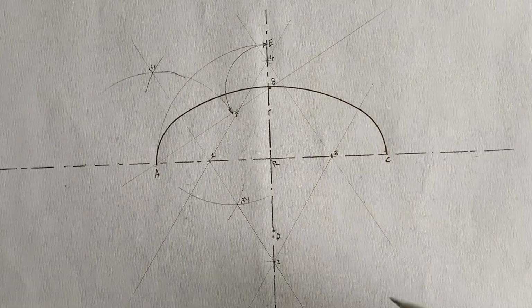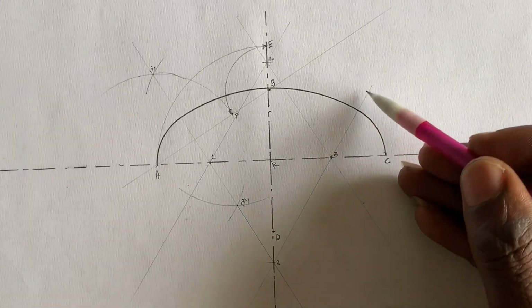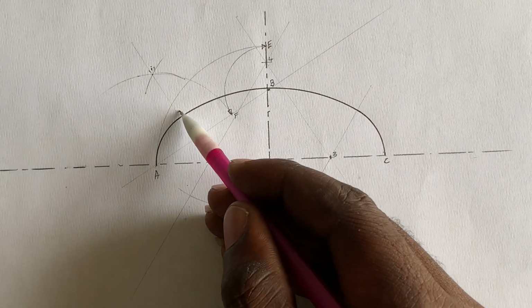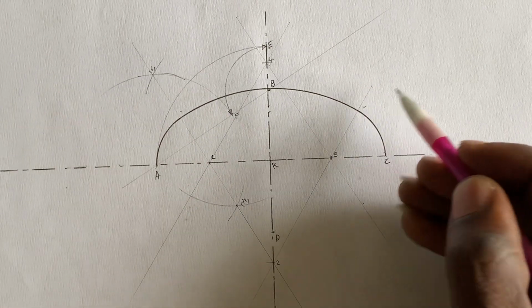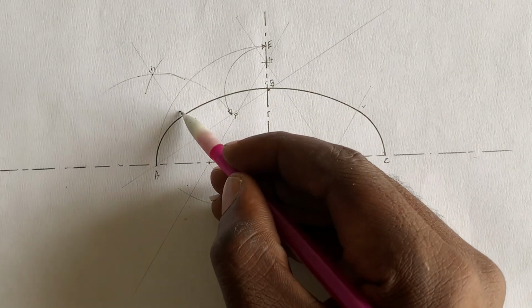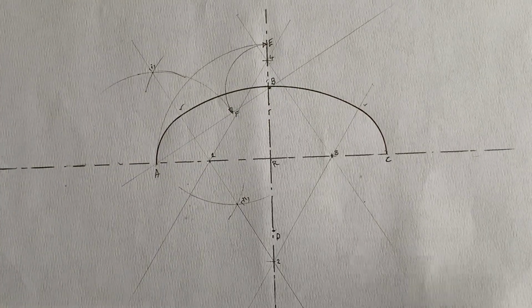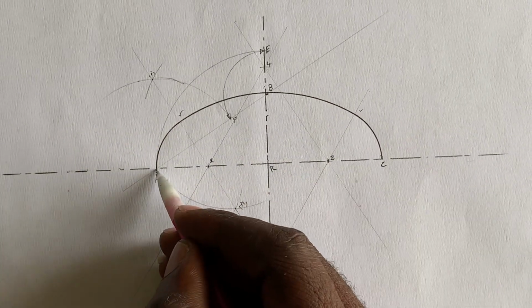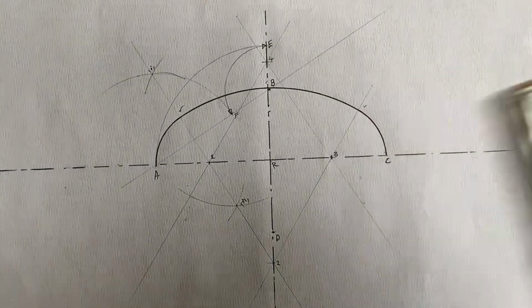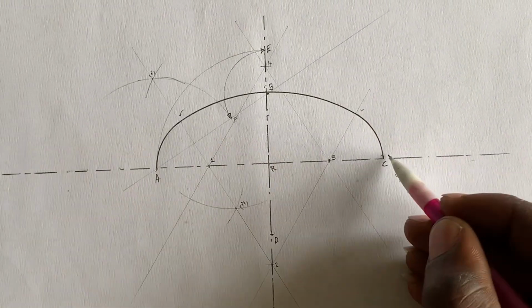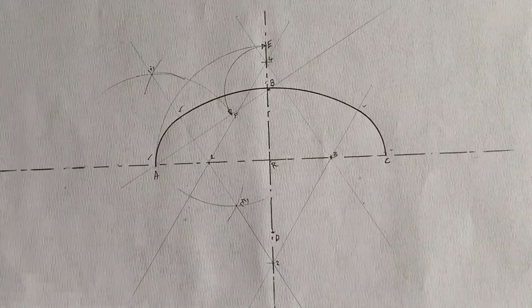That is why, my brother, I was saying don't stop here, further extend it down. That's where the marks are actually lying. They will check whether your ellipse is touching nicely there. When they mark, these are the crucial points. From A to C, is it the real 100 millimeter? These are crucial points that you have to take note of.